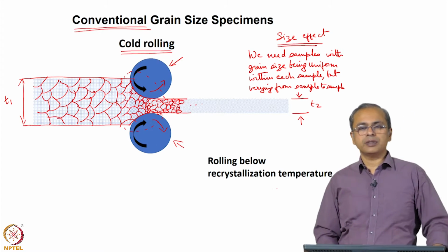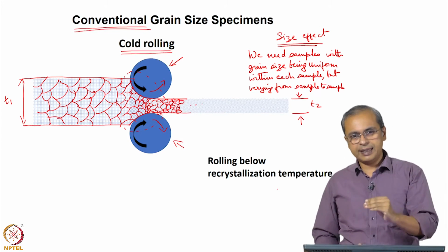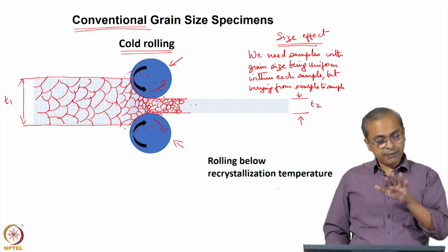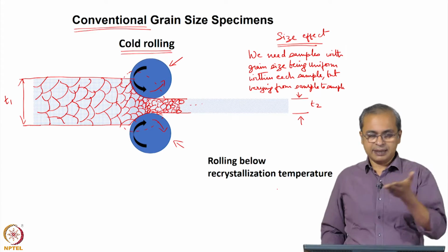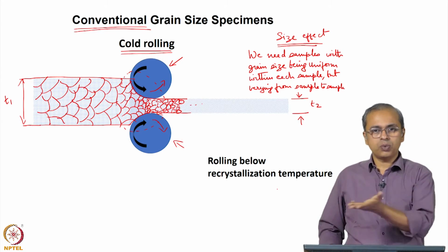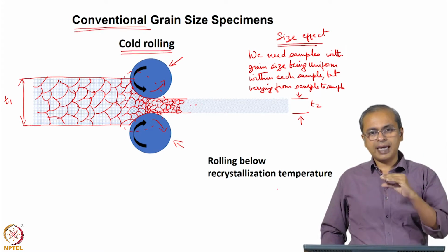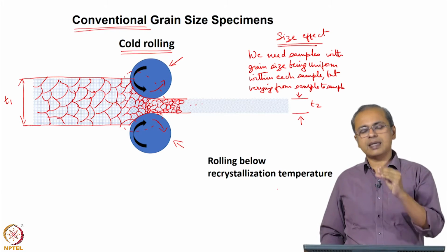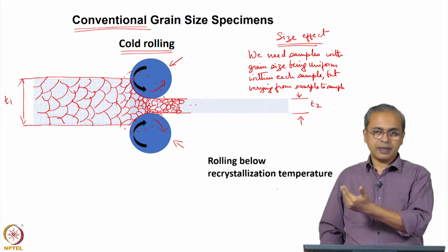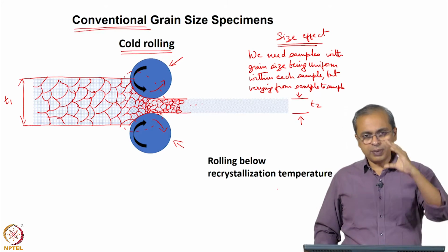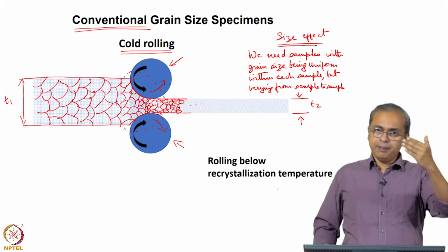So, this is a typical rolling process, and there are some restrictions. I mean, this is a schematic, so it looks like you can take a very thick material and roll it down to a very thin material. Normally, and in fact, it is true that you can eventually do this. Normally you will not do this in a single pass, each time it goes through it is a pass. So, you send it through and you get it out to the other side. There are restrictions on what you can do in a given pass, given the stresses that are involved, given the kind of behavior of the material and so on. So, if you want a nice smooth sheet coming out, there are some restrictions on how much you can reduce. So, reduction per pass, there will be some restrictions. Within those restrictions you can do it, but you can continue this repeatedly.